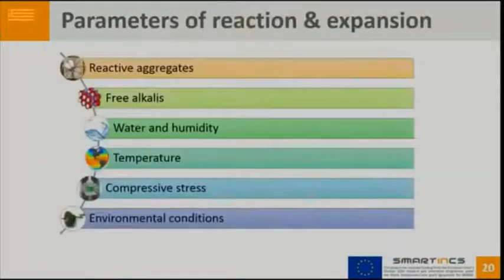The main parameters that lead the alkali silica reaction process or damage are reactive aggregates, free alkalis, water, temperature, compressive strength, and in general environmental conditions.